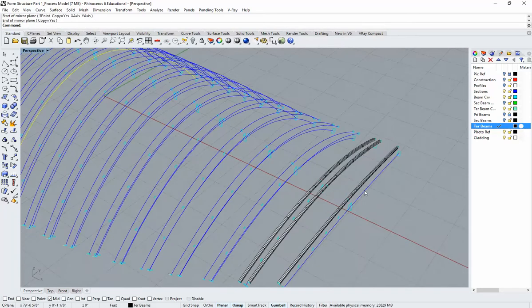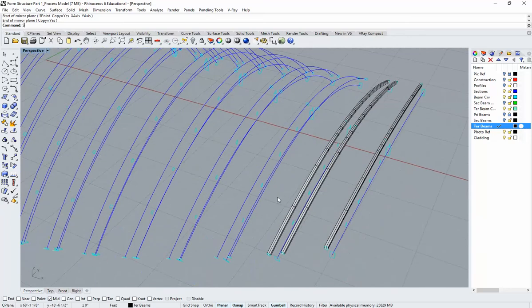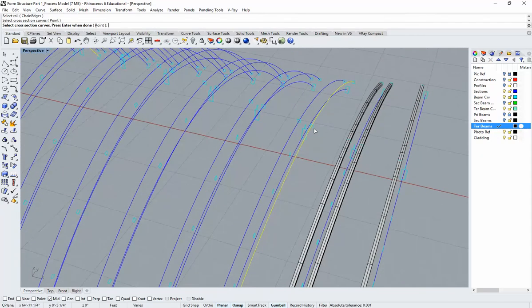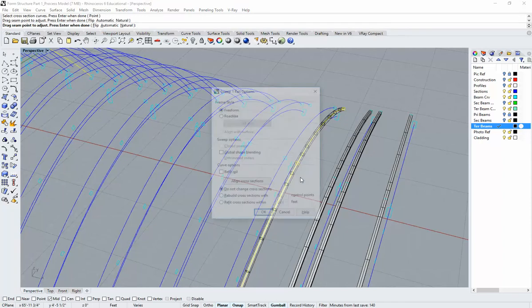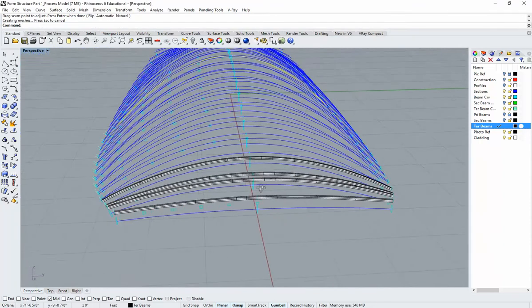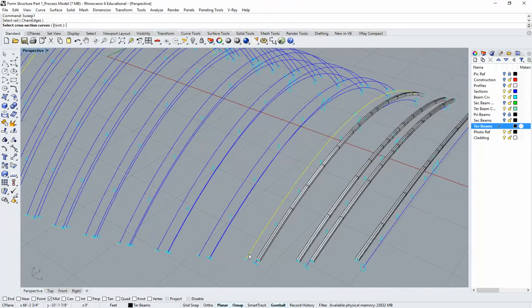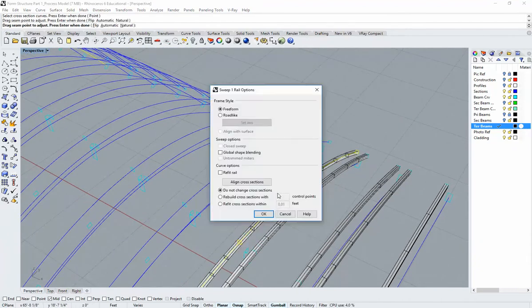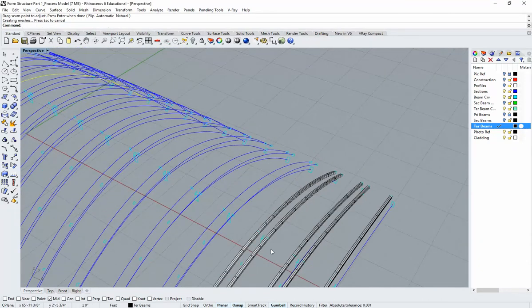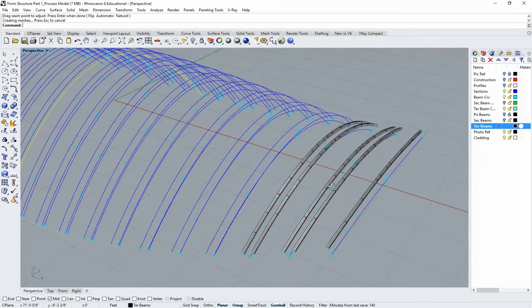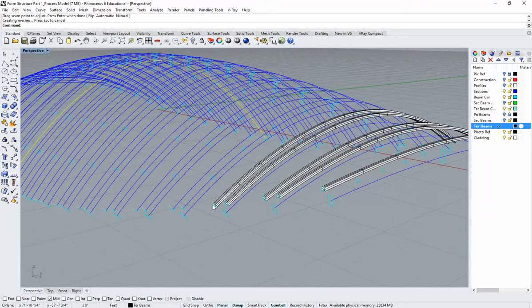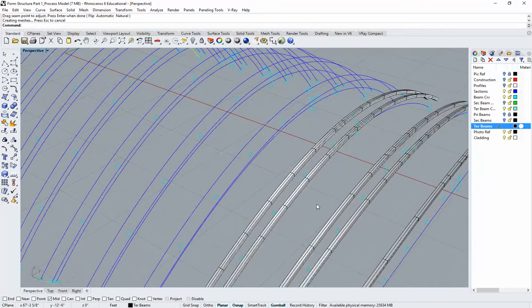Hopefully this is starting to sink in terms of its repetitive methods. But because we have curvature in the system, unfortunately there's quite a bit of repetition if we want to model this properly. You know, because almost every section is unique. Of course, it's symmetrical, but at least within the quadrants, they're all pretty unique curves, and they end differently down here, so you just have to do the rotations. Okay, I'm going to pause it here. I'm going to wrap these up, and then we're going to do the skin.